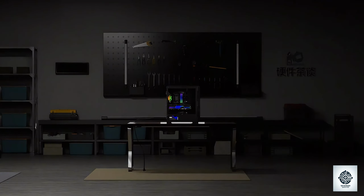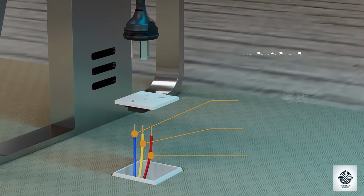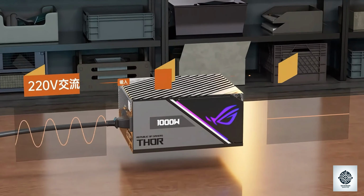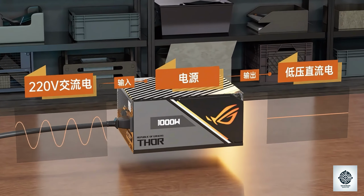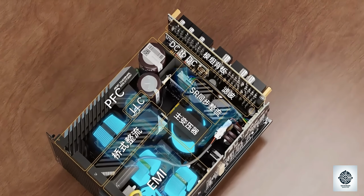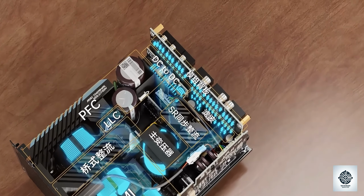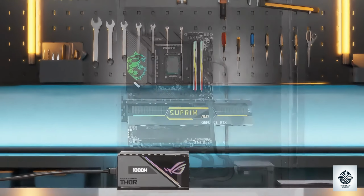If you're considering choosing a power supply, you first need to understand its function. Household outlets provide 220-volt alternating current AC, but computers require low-voltage direct current DC. The main function of a power supply is to convert AC to DC and provide various voltage levels. After the 220-volt 50 Hz current enters the power supply through the outlet, it passes through an EMI filter, PFC, rectifier filter, and transformer. The voltage is then reduced to 12 volts, 5 volts, and 3.3 volts and sent to the computer components via cables.